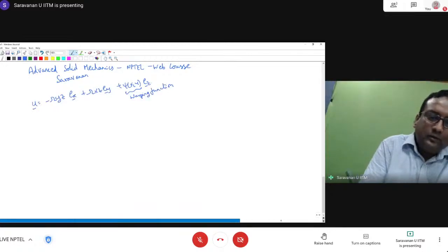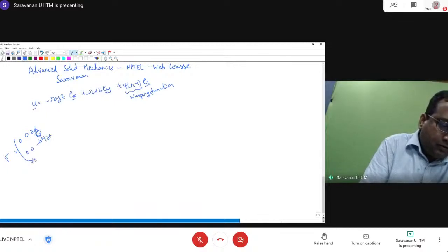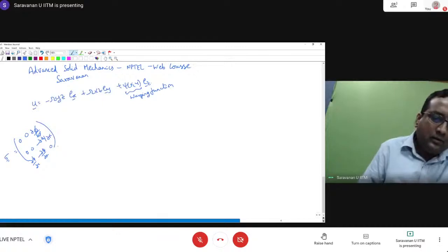You then introduce a Prandtl stress function phi such that the stress is given by a matrix with entries zero, zero, dou phi by dou y; zero, zero, minus dou phi by dou x; dou phi by dou y, minus dou phi by dou x, zero.